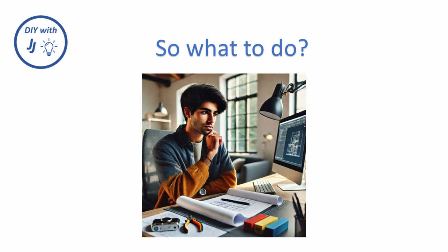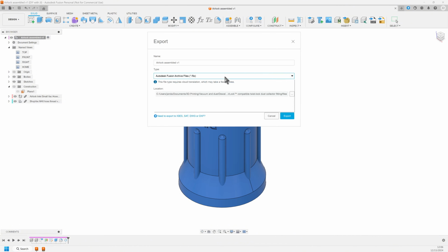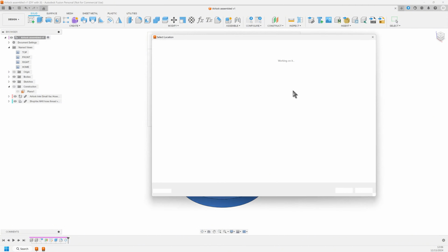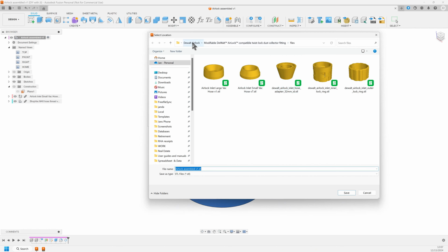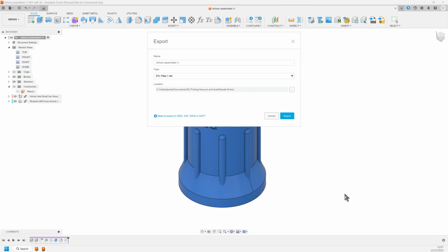So how should you handle modular design? First, keep the components as simple as possible and save the logos and other fancy references until after the parts are delinked and combined. Or if that's not possible, don't worry about combining the parts, but use other methods like exporting to an STL if you're 3D printing. You saw in my other video how that combines the whole thing anyway. The time I save reusing some modules in new designs will ensure that I keep using modular design when appropriate. Once you know the traps and what to expect, it becomes fairly painless.